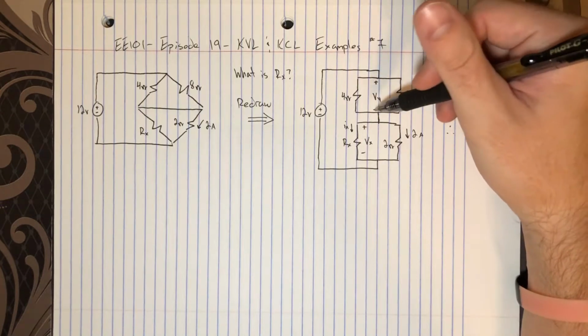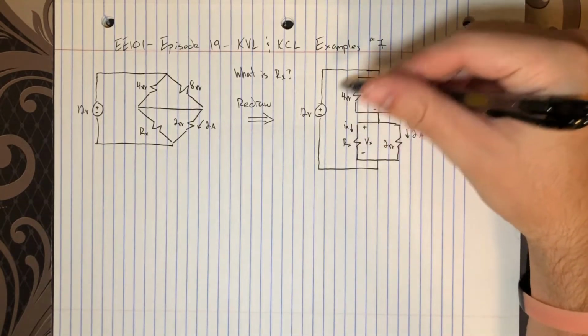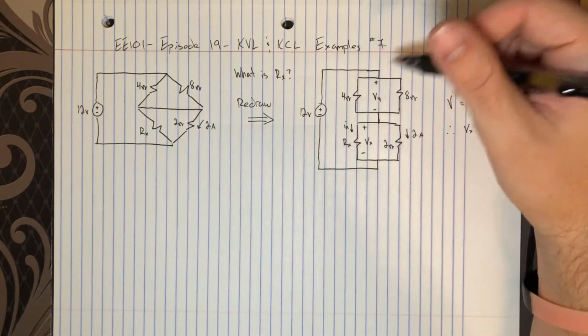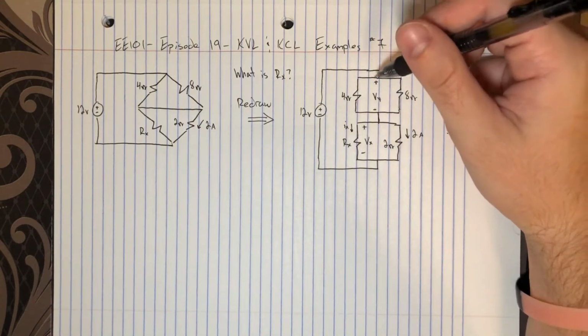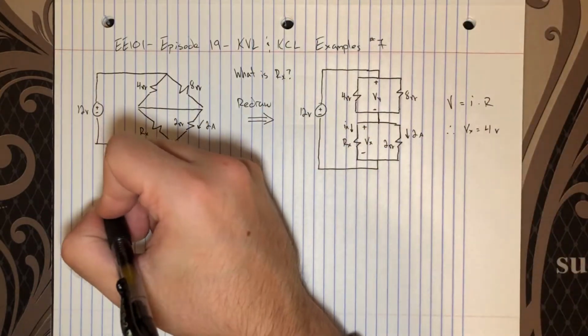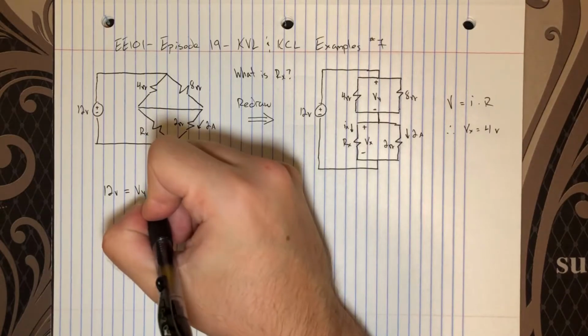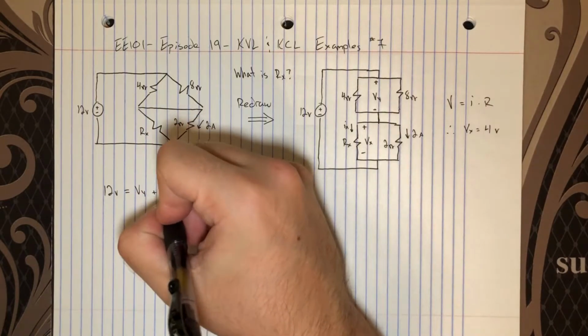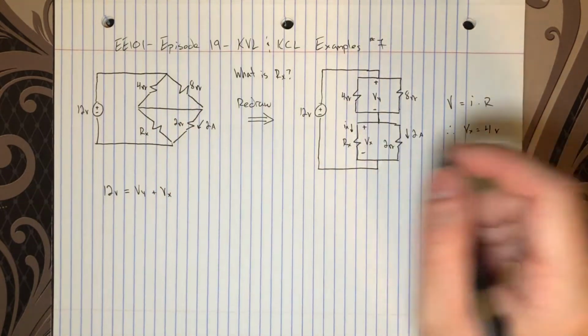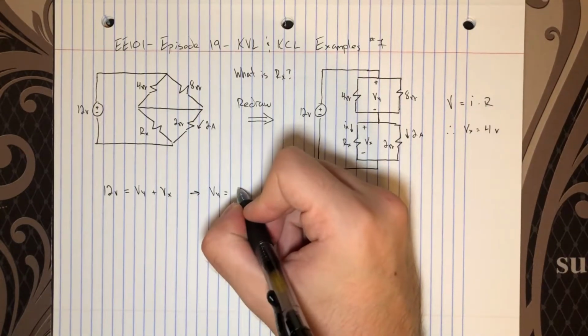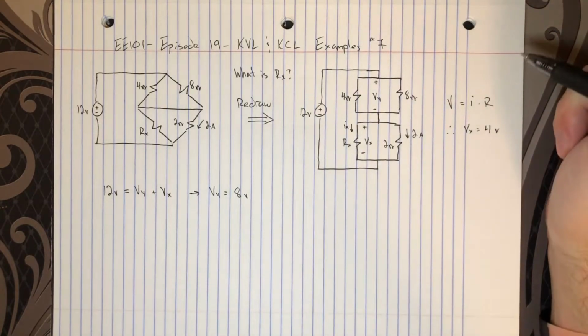We're going to step down Vy and Vx, and for KVL to work out, we know that the step ups have to equal the steps down in potential. So it's simple to write that 12 volts equals Vy plus Vx, and given that we already know Vx, therefore Vy equals 8 volts.